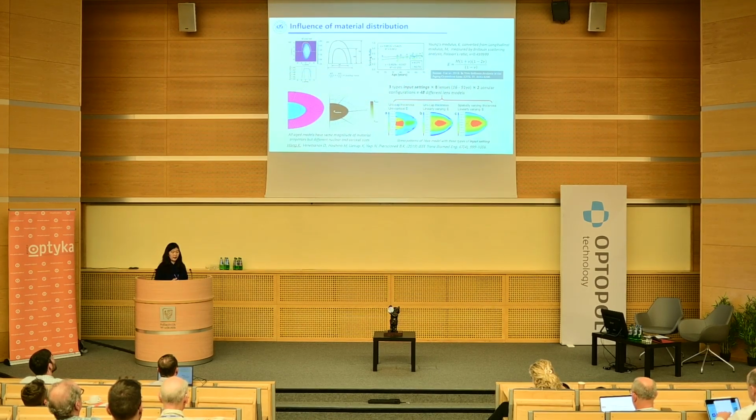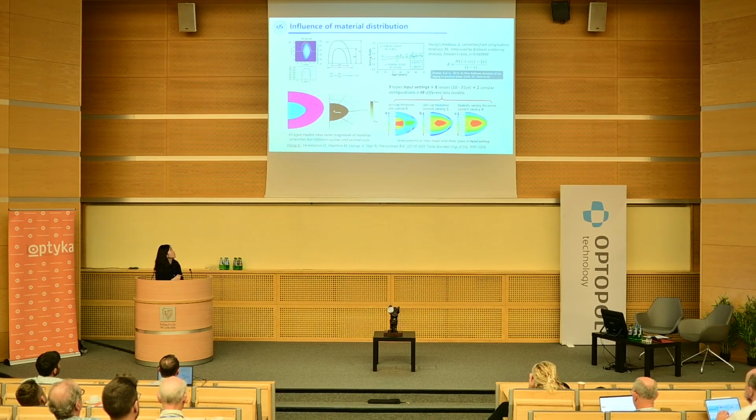So we have created a series of lens models using the ratio between the plateau region and the whole lens. And then we wrote a code in ANSYS by ourselves to assign material properties to different nodes using a linear interpolation method.